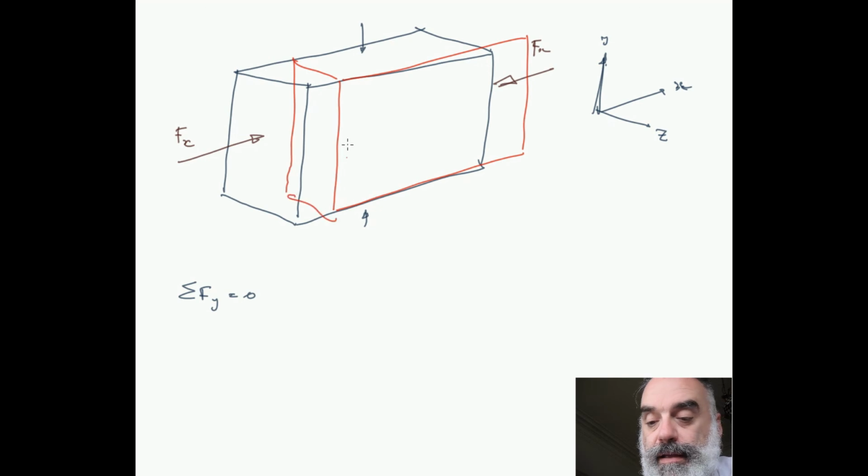Okay, again, under F equals ma, if there's an imbalance, so if the wind load or the person leaning on the bench is not met by a resistance from the ground, friction resistance, or some bolts that bolt it into the ground, which produce an equal and opposite force in the opposite direction, then that thing is going to accelerate in the x direction, positive x direction, if this one is greater.